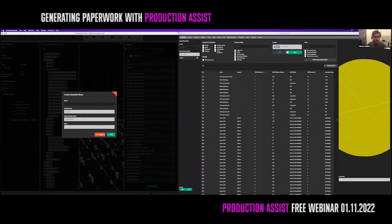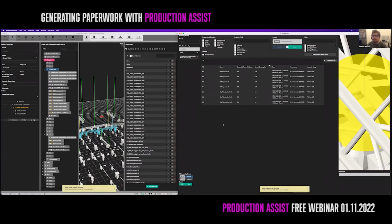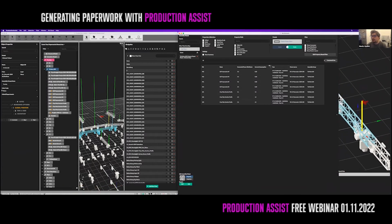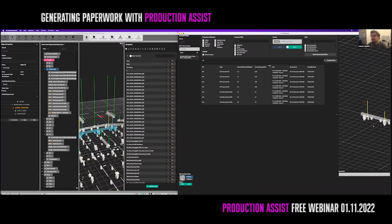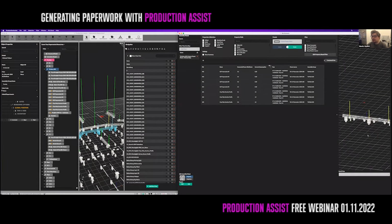Again, we will start with a preset in here. So there are multiple ones, and we will now start with the fixture power patch. If I'm selecting this and call it fixture power patch, I can create it. You get an alert that it has been created, and you see that it pops up here in the worksheet view. If I'm selecting this, you see now there are much fewer entries for this specific assembly group. Also, in the 3D renderer, you now only see this specific truss line or this specific object that are part of that assembly group, which is a handy feature if you want to assemble it.